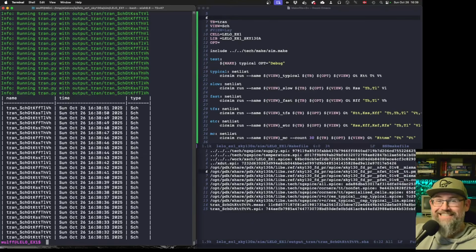Multiple tens of days is how I want to describe it, from when you start with a blank wafer until you actually have finished circuits. And each one of the steps, implanting boron or implanting whatever phosphorus, will have a certain precision. And that precision is not the same every day, every week. Which means that from wafer to wafer, you will have different transistors.